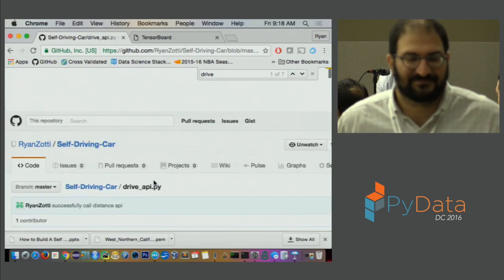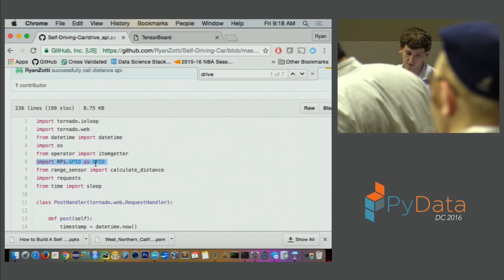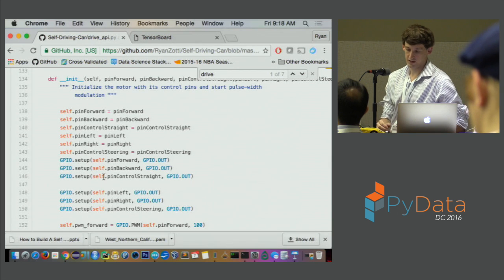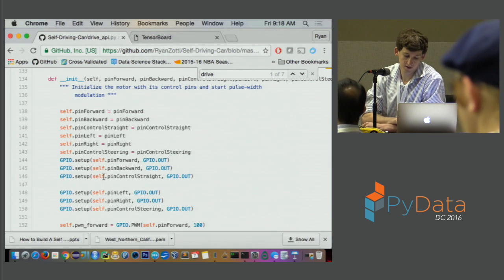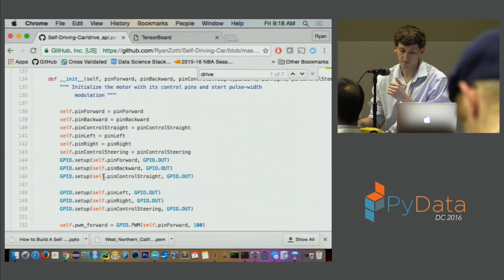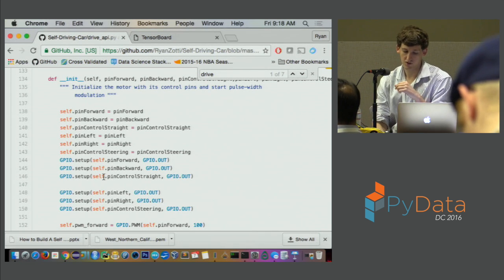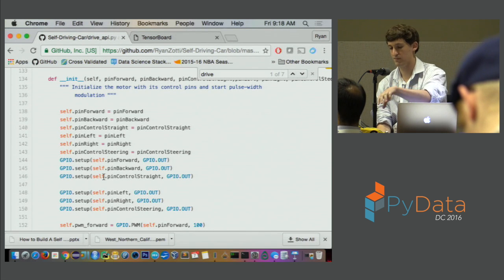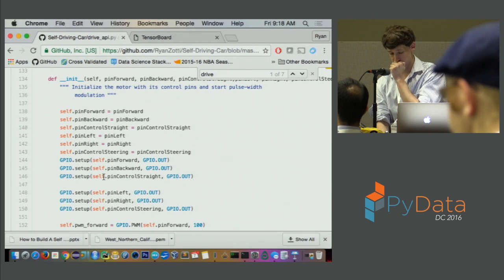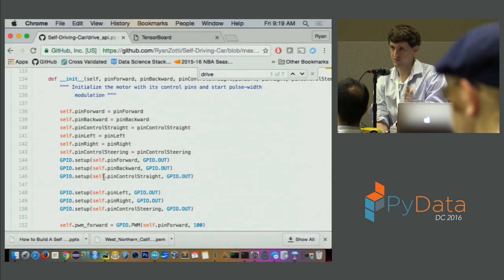Basically, whenever you interact with the Raspberry Pi, you have to import basic Raspberry Pi packages, or just one library. There are different pins on the Raspberry Pi, and depending on how you do your wiring, you can turn various pins on or off. Via soldering and connecting some wires to the actual motor of the car, you can control it. My particular car has a motor for steering, for going left and right, and a stronger motor in the back for going straight. So if I turn on the motors for going straight and for going left, the car will go left.